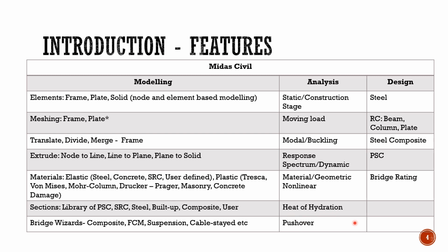In order to perform pushover analysis for the bridge structure, MIDAS Civil has a dedicated tab for it, which helps us identify the plastic hinge location, the yield status of the plastic hinge, and the performance point as per ATC 40 and FEMA.